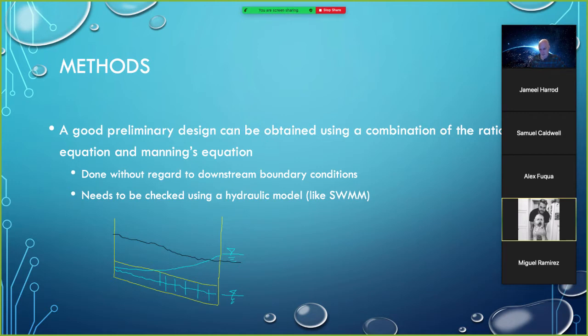We can accommodate that if we have enough vertical real estate by taking advantage of vertical drops along the lines of, we use magenta. So we can have a pipe that goes like that, and then we literally can drop it vertically and continue working our way downhill. The vertical drops give us the ability to exercise some control over both velocity and a little bit of control over the downstream boundary behavior.